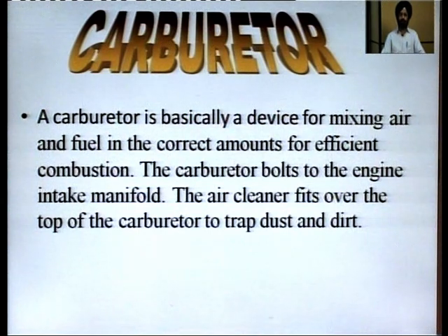Where is the carburetor placed in the engine? The carburetor bolts to the engine intake manifold. The air cleaner fits over the top of the carburetor to trap the dust and dirt. So after the air filter there is the carburetor, then the inlet manifold, and then the engine.